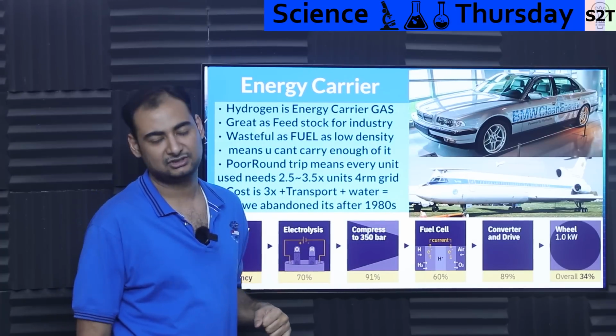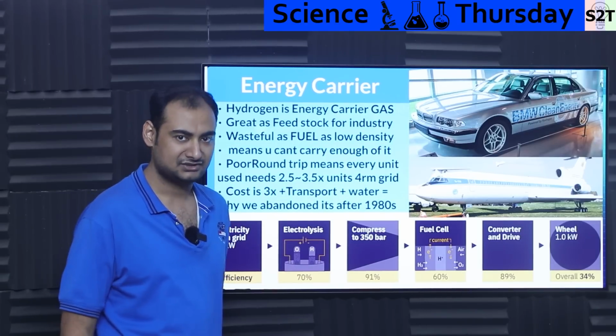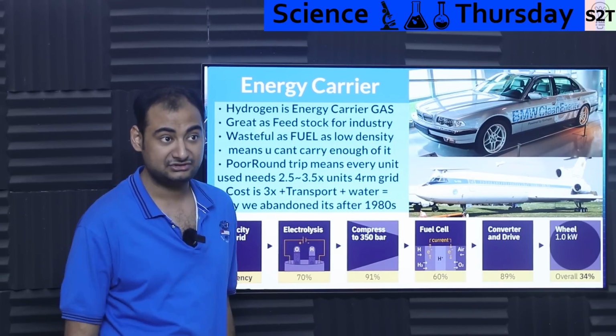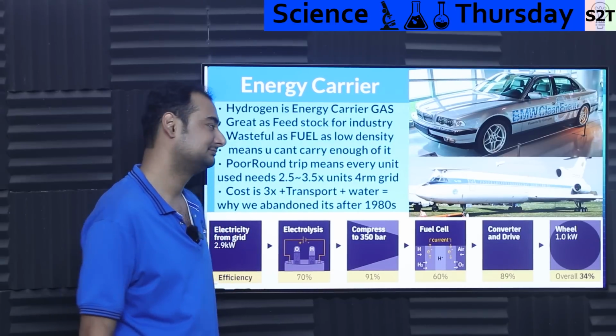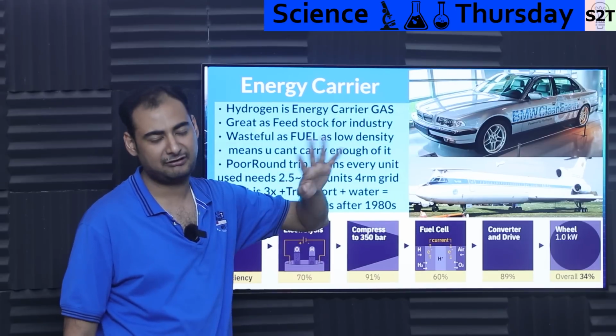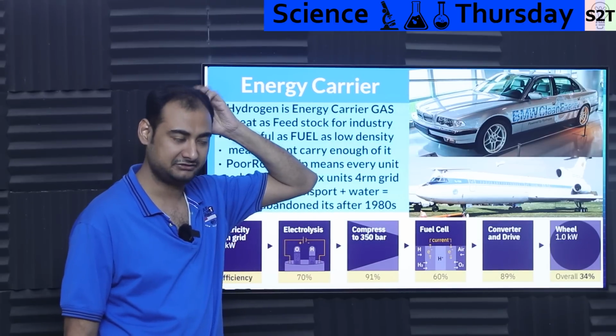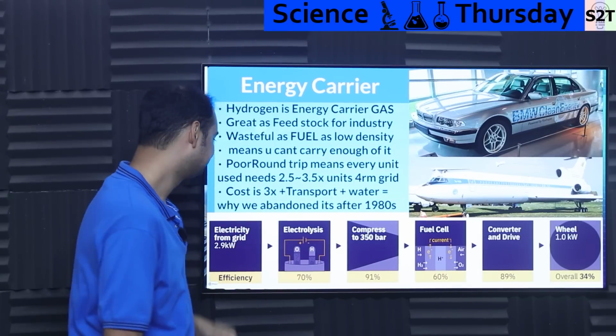Well, you can utilize a solid metal halide. Like, why can't we do that? Well, it's 10% by mass, meaning to carry 10 kilograms of hydrogen, you have to carry 100 kilograms of solid metal powder. Yeah, no, not happening on a plane. Maybe 5 to 6 companies did try to do that, and again, then they realized they need cooling, more cooling than a battery.